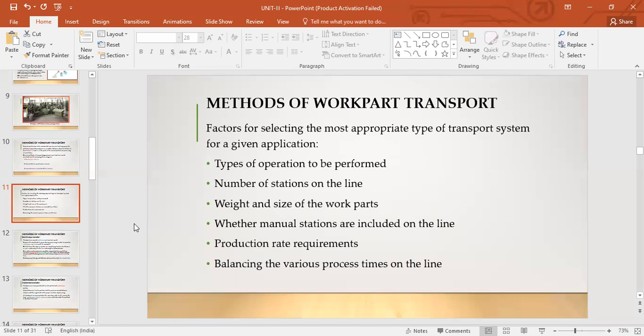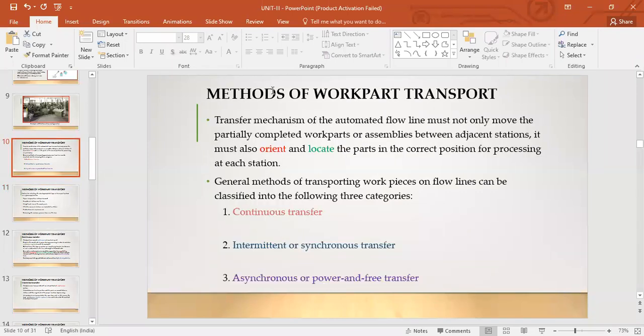So there is a terminology in machines called starving. You call a machine starving because it is not being fed the work parts, it is idle basically. Or if there are more work parts waiting for this machine to be processed, then that is also another disadvantage, right? That you have this pile up of work pieces. So that is what line balancing considers. So even that has to be taken into account. So those are your factors. Clear so far, right?